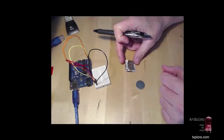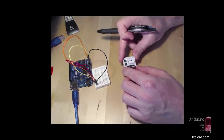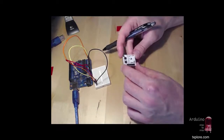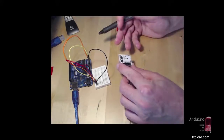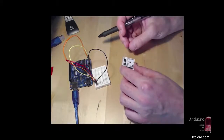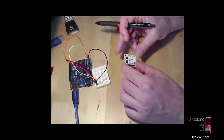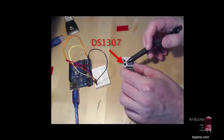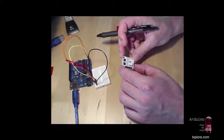So in this demo I'm going to show you how to connect the real-time clock breakout and set the time on it and then retrieve it. For that I'm going to use this breakout board. This particular one is called TinyRTC version 1.1. I'll show you the website from where you can get the libraries and other information like schematics for this particular board. On the PCB, this chip actually implements the real-time clock. This is a DS1307 real-time clock integrated circuit, which is very popular.